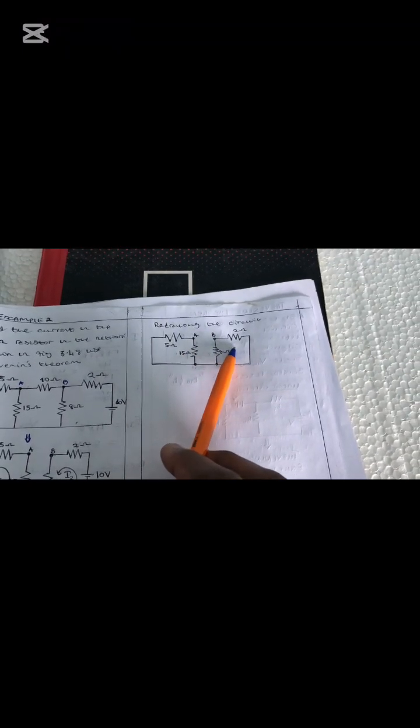To find our Thevenin resistance, we have to redraw our circuit by removing the 2 voltage sources. Since we've removed the 2 voltage sources, this is how the circuit will look. If you look at the 5 ohm resistor here and the 15 ohm resistor here, they are connected in parallel. Also in our second loop, we have an 8 ohm resistor and a 2 ohm resistor that are also connected in parallel. After finding them while they are connected in parallel, the next thing you will do is add them, since they'll be connected now in series.